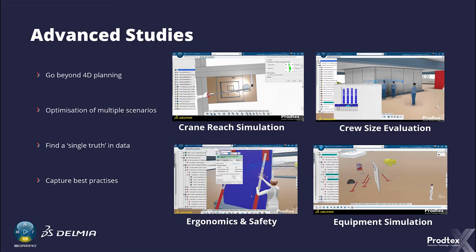The second might be for the lower floors of the building, you could actually use a mobile pump truck next to the concrete truck. The third might be maybe you're going to use a portable concrete mixer which is dropped onto the floor which is needed, and the concrete is going to be pumped up to that portable mixer. Of course, there could be loads of different options throughout the site as well, which I won't mention here.